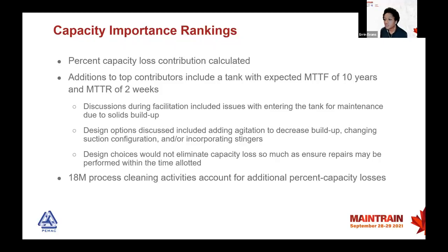Another outcome is the capacity importance rankings, which are calculated in terms of percent capacity loss. Additions to the top contributors were a tank that had an expected MTTF of 10 years and a mean time to repair of 2 weeks.